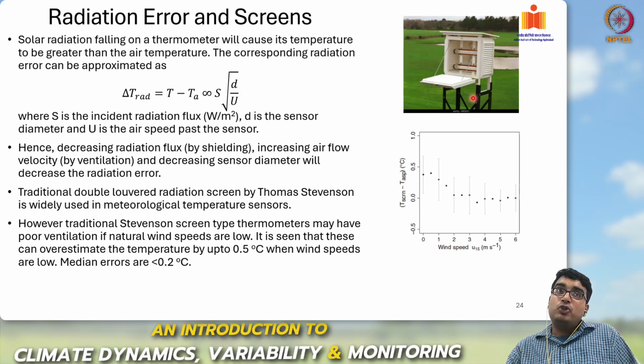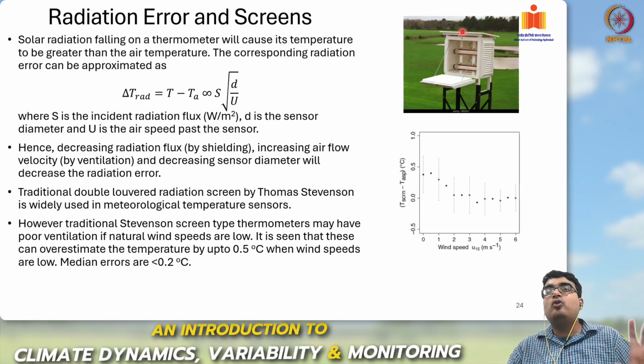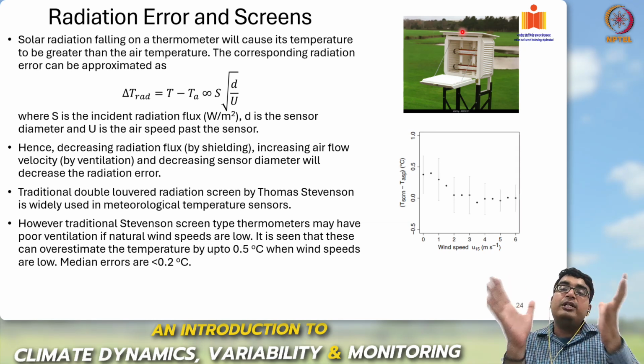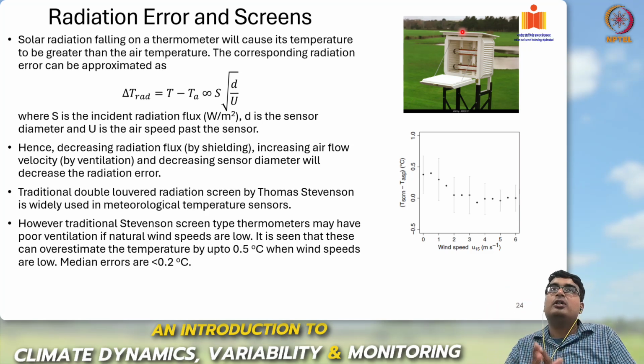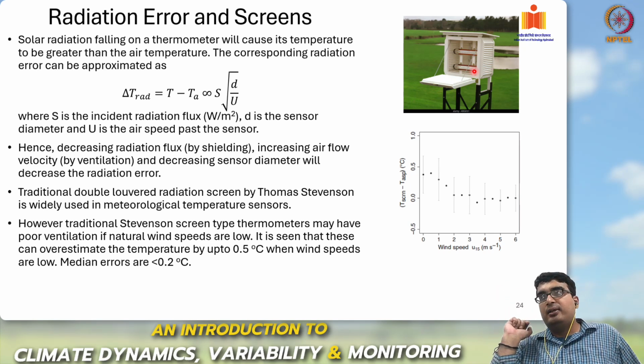So usually all air temperature measurement devices are shielded, that is, they are put in a box, a ventilated box within which air is flowing through these outer kind of screens. So air can go pass freely through, but because of these shields around, direct solar radiation cannot enter.